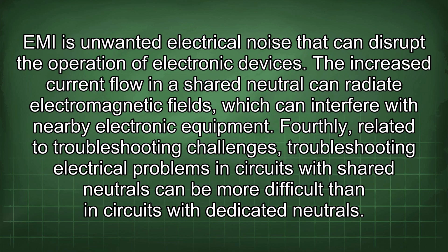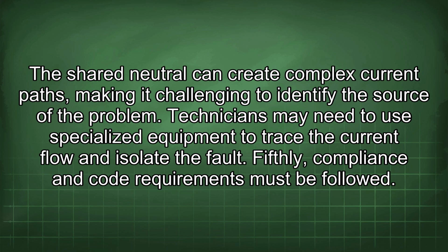Fourthly, related to troubleshooting challenges, troubleshooting electrical problems in circuits with shared neutrals can be more difficult than in circuits with dedicated neutrals. The shared neutral can create complex current paths, making it challenging to identify the source of the problem. Technicians may need to use specialized equipment to trace the current flow and isolate the fault.